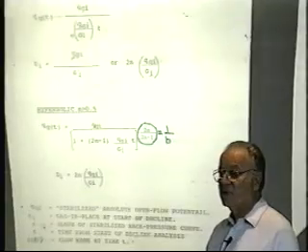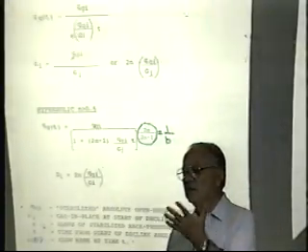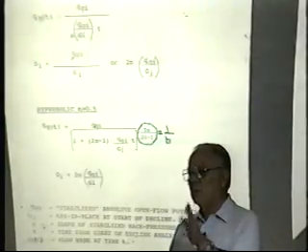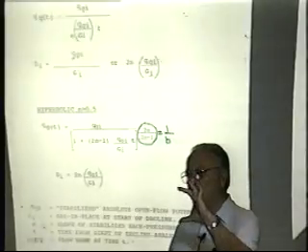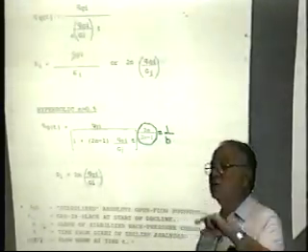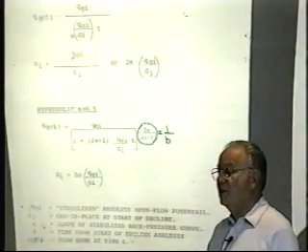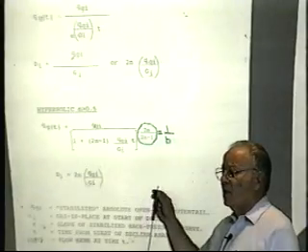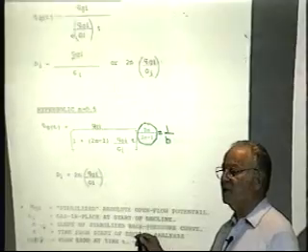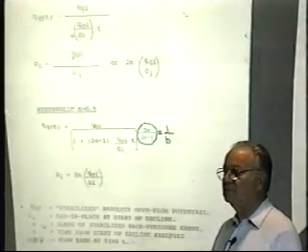All the gas was there. To give you an idea where we're coming from, if you have a layered no crossflow reservoir where the properties are such that you have quite a bit of differential depletion between the two layers, when you shut a well in, the pressure you're going to see is the pressure of the more permeable layer. You never see the other pressure. So when you're trying to do a history match on that pressure, you're assuming implicitly that's the same pressure that exists in the other layer, and it isn't true.